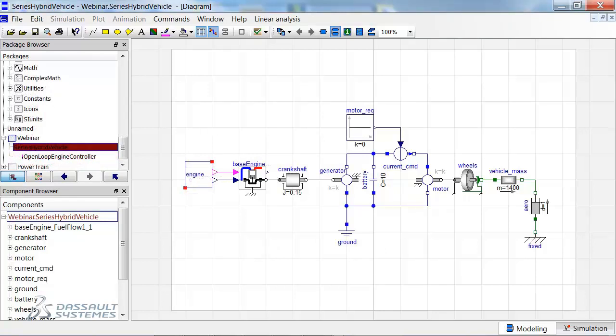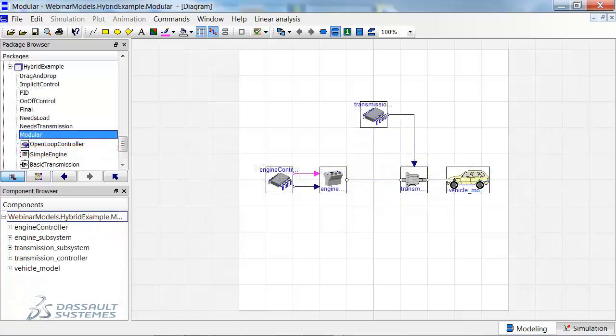We do this, in turn, for the engine, transmission, transmission control, and vehicle models. After some purely cosmetic changes, we have the following vehicle model. The result is that we have decomposed our system into subsystems. But we aren't quite done unlocking the potential of the configuration management features in Dymola. In order to fully express the configuration management problem, we need to define interfaces for each of the subsystems.